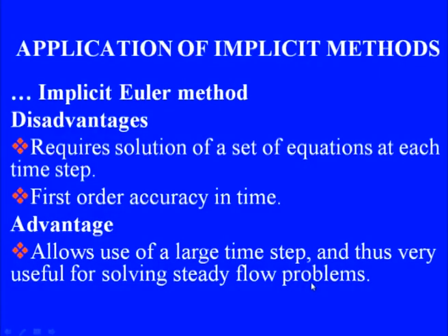Whether our aim is to obtain a steady state solution of a heat conduction equation, or an advection-diffusion equation or a full Navier-Stokes equation, we can use implicit Euler method to quickly obtain, using large time step values, our steady state solution. So that is the big advantage which our implicit Euler method provides. Its stability properties are so good that this is the preferred choice for solution of non-linear time dependent equations.